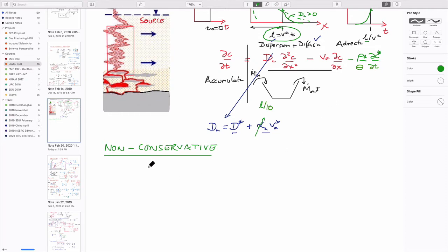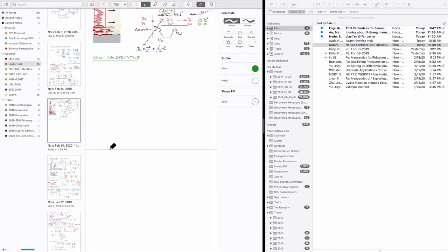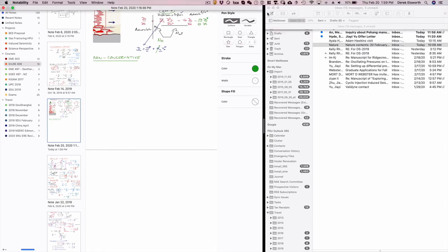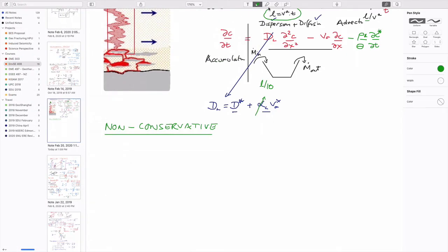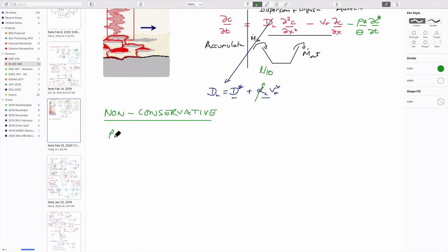And so this extra term, which we'll come back to, represents, why does it keep on doing that? It must hit something bizarre. Is that this term allows retardation to occur. And so just to define the terms, D is equal to the bulk density of the aquifer. And it's commonly, for sands, would be a bit less, but something like 2,000 kilograms per cubic meter, ballparkish.